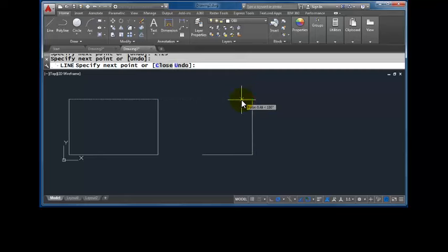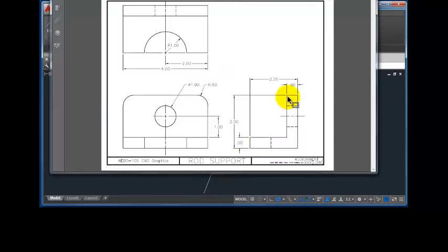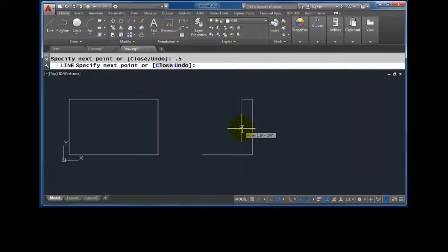The length of this top edge in the right side view is 0.5. To enter this edge correctly, I need to do a little math. I'm coming down this edge here. I know the total length of this view is 2.5, but I'm going to stop 0.5 or half an inch short, so this edge is actually 2 inches long. Track to the side, hover over that endpoint, and click where those intersect, and then close.